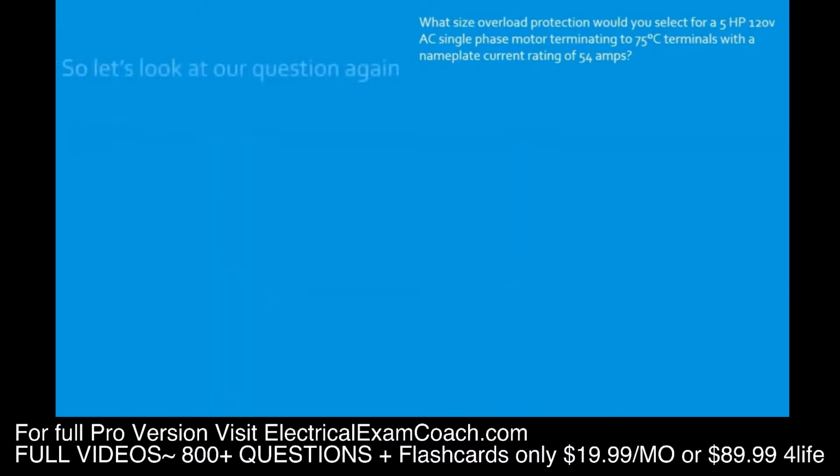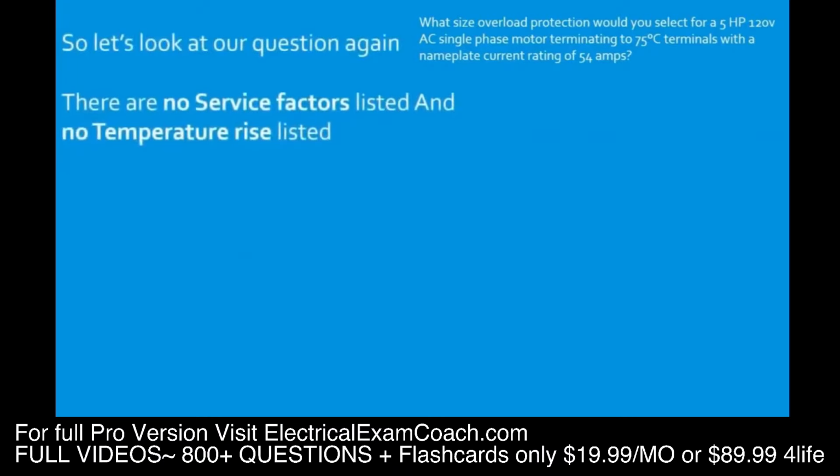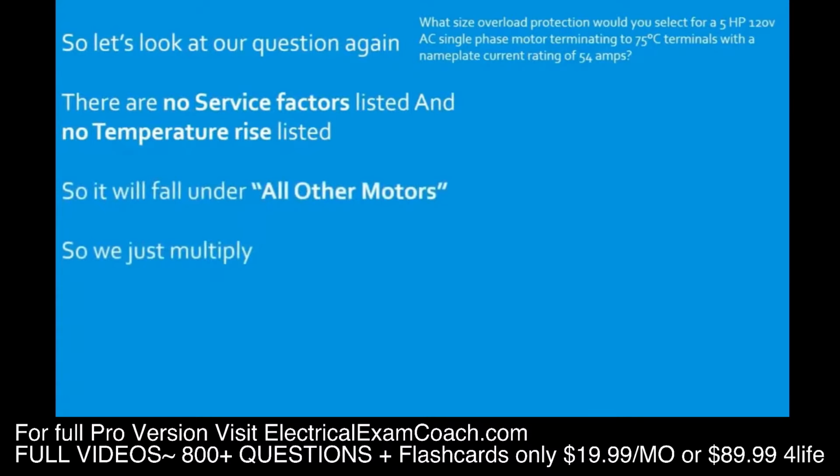So let's look at our question again. There's no service factor listed and there's no temperature rise listed, so it will fall under all other motors. So we just multiply. We take our FLA, which was 54 amps, multiplied by 1.15. That's going to give us a new total of 62.1.